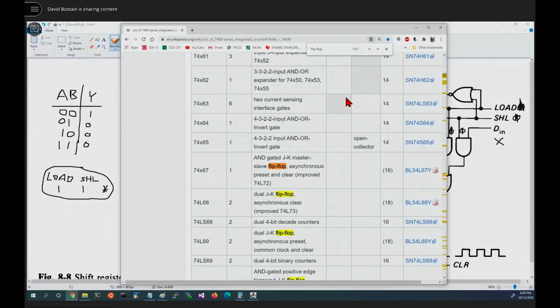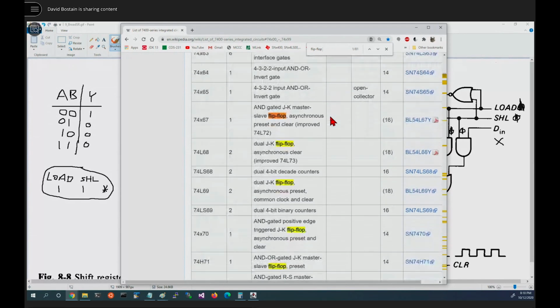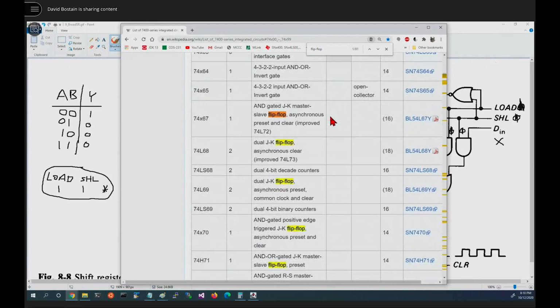Okay, let's shop. Let's assume we were going to go out and find a flip-flop to use in our circuit. We know a little about them right now. Notice these all have the potential in the X position to have a letter like L, LS, or S, or HCT, or A, ALS, some of the other kind of sub-architectures of the 7400 series. We're working with the one that has nothing there. It's basically the standard, the original series.